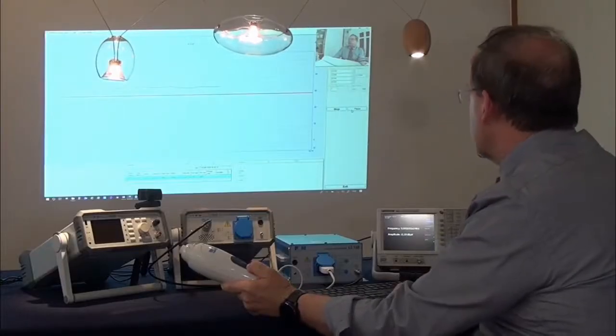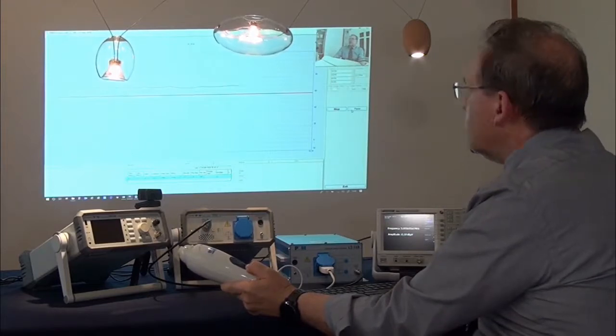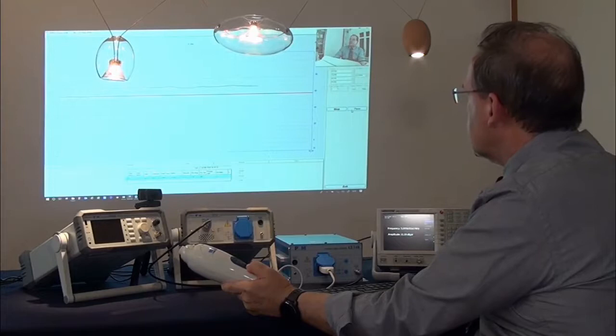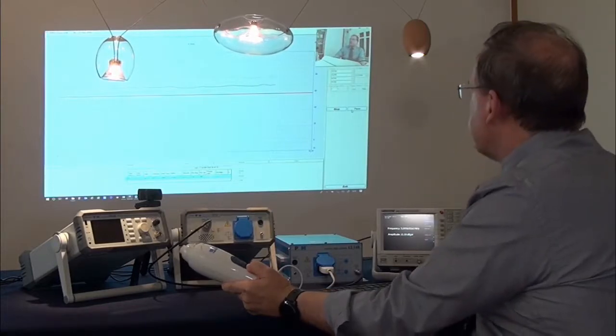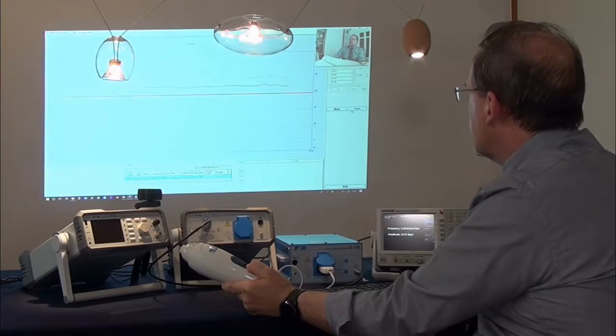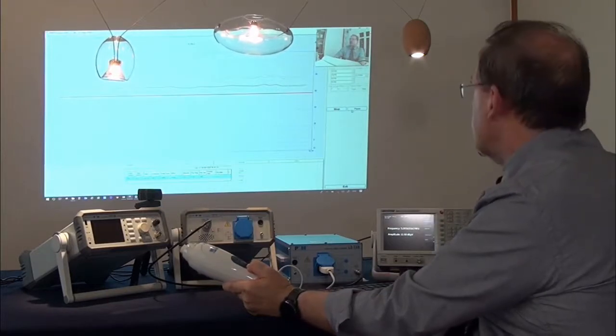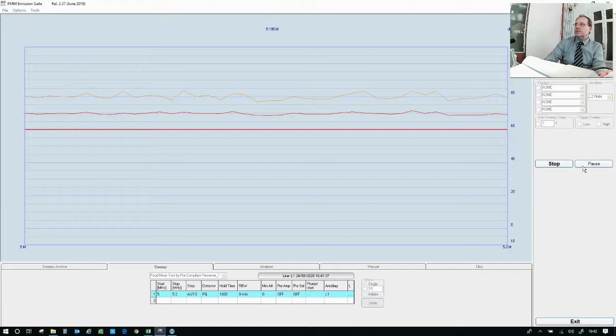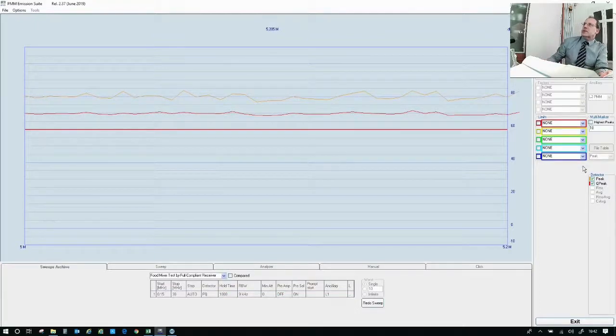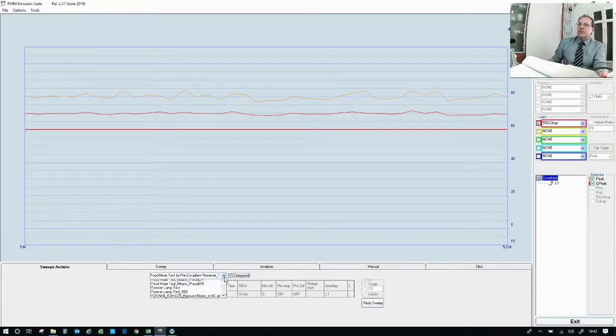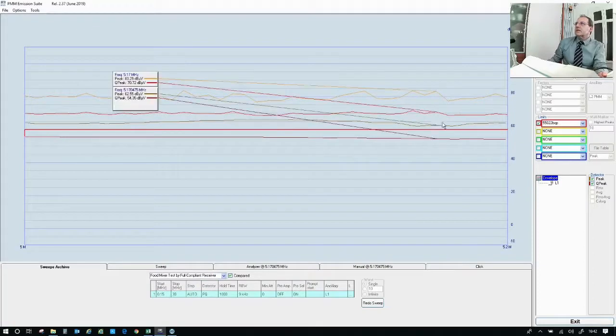It's taking, of course, always a longer time with this pre-compliant receiver because it's not FFT, and we can see almost everywhere the signal is over the limit. Okay, now it's finished, and we can immediately compare this with the curve for the full compliant receiver. Look, now there is again a difference. The full compliant is below the limit and the pre-compliant is still over.